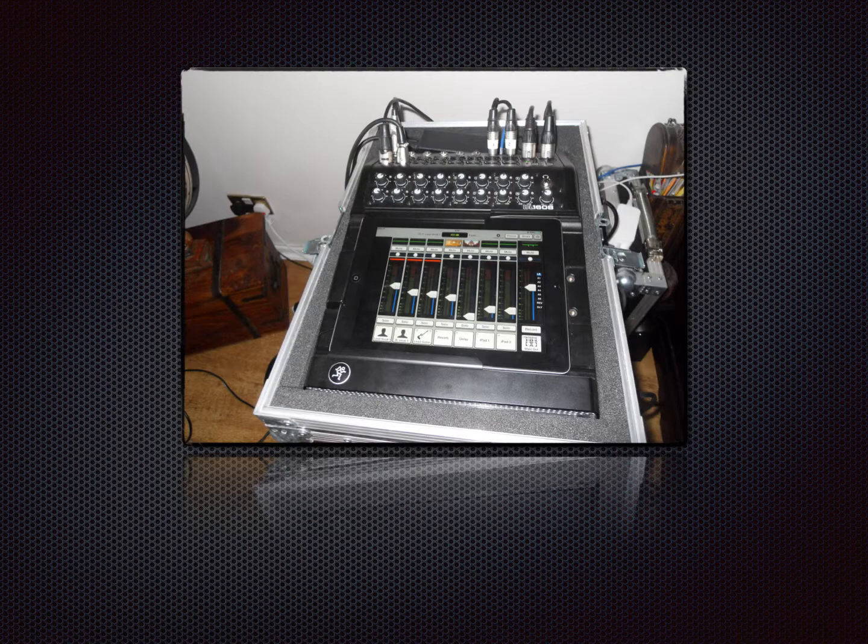It's important to use balanced signal leads where possible. These leads use cable with 2 cores and a screen and send the same signal along both cores at opposite polarities. This enables the mixer to cancel out any electrical noise picked up by the cable, getting rid of any unwanted hums or buzzes. Selecting the correct microphone is also essential in terms of frequency response, polar pattern, which means its directionality, and physical sturdiness.